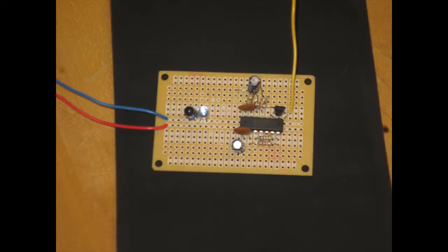The idea behind this heart rate monitor is simple. As the amount of blood being pumped through your veins varies because of your pulse, the amount of infrared light that is reflected back at the infrared receiver varies, and thus causes a varying voltage signal through the circuit.